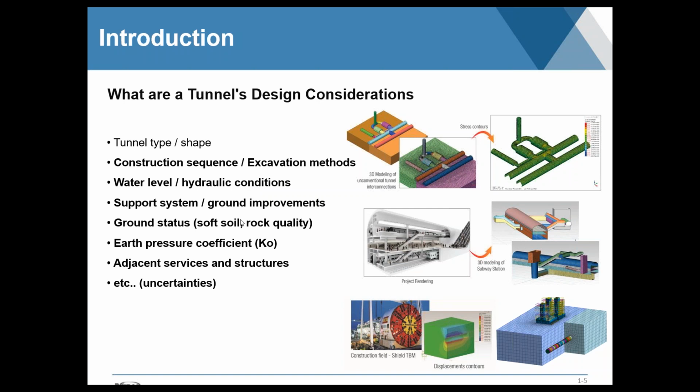Are we excavating in soft soil or in rock, or are there stretches where we have a combination of both, as well as other things that only geotech engineers would really get a grasp on, like considering the pressure of the earth, the lateral pressure, and if there are existing structures in place, how would this new excavation, this new project, affect something that's nearby, adjacent, that's already in place.